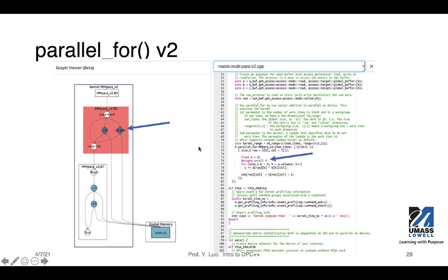Now, in the previous design, we didn't have this pragma unroll factor. The unroll factor is a way to increase the efficiency of loop operations, especially if there are no dependencies between these loops. And with this unrolling, we can use replicas of the design to basically replicate the loop iteration and use more resources to take advantage of the parallelism.